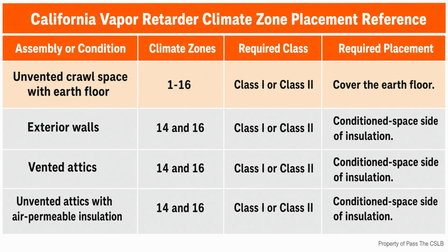Upper over lower follows the same drainage logic as shingles. Water running down the face stays on the exterior side of each lower course. Reversing that lap creates an edge that can direct water behind the layer. At vertical joints, the larger overlap gives continuity where one run ends and another begins.